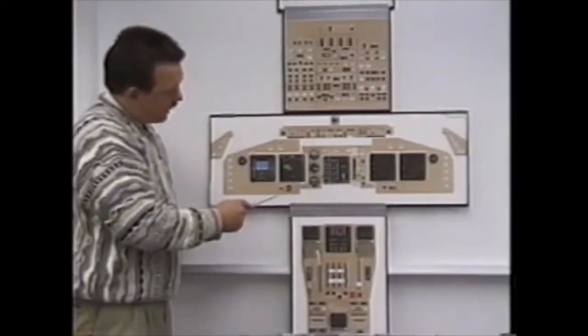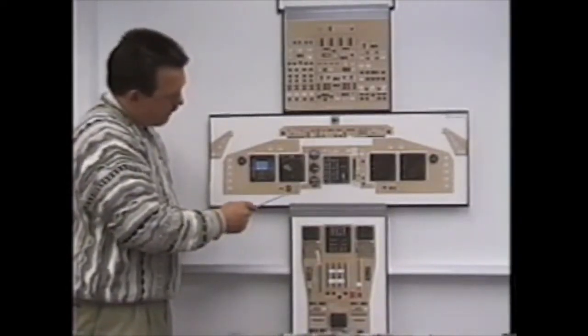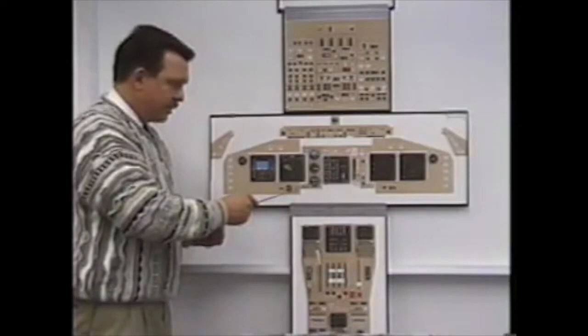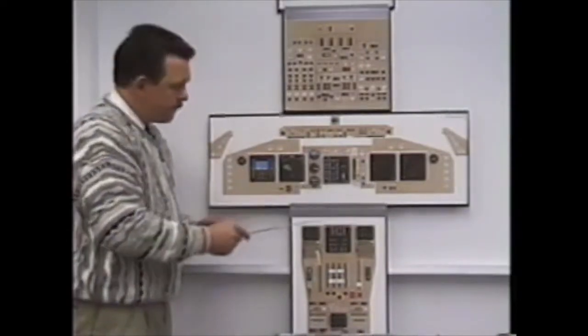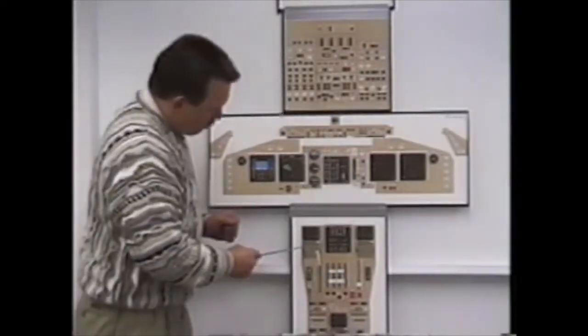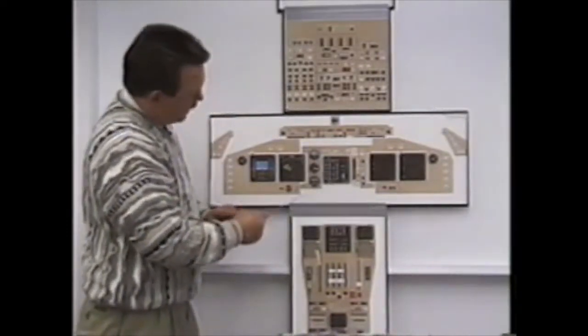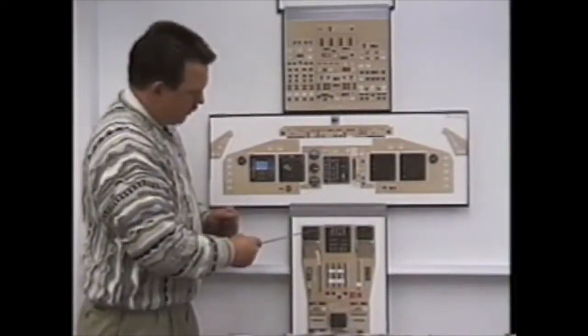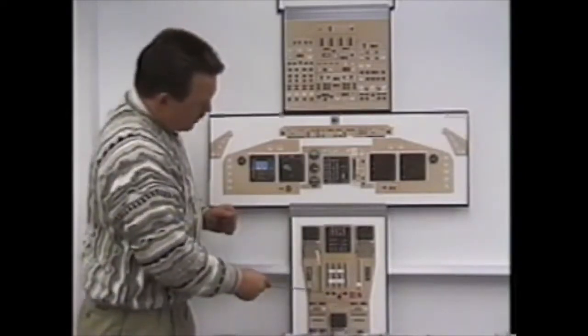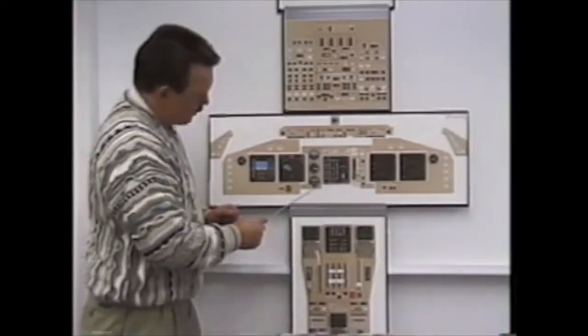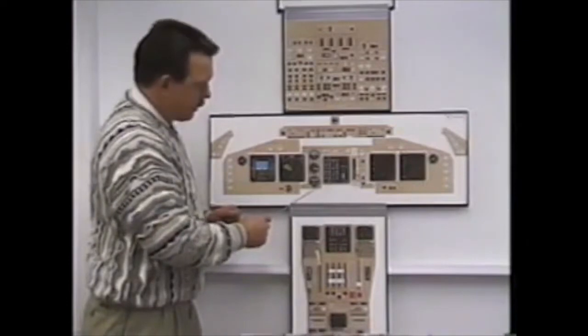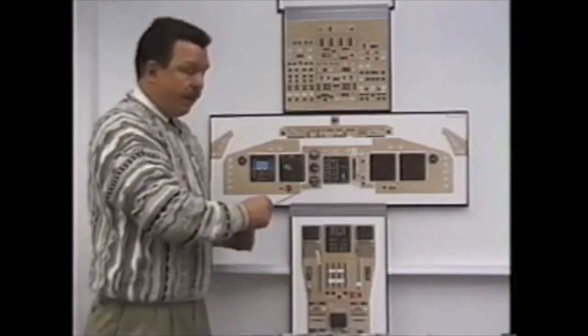Once the light off is indicated, we have to respect the 535 start EGT limit, which is indicated by the first red line. We must have an oil pressure indicated by 40% N2. We must have an N1 indicated by 40% N2. Once the first officer brings the fuel lever up to run, we have 2 minutes for the start EGT line to disappear, indicating that the engine is stable.